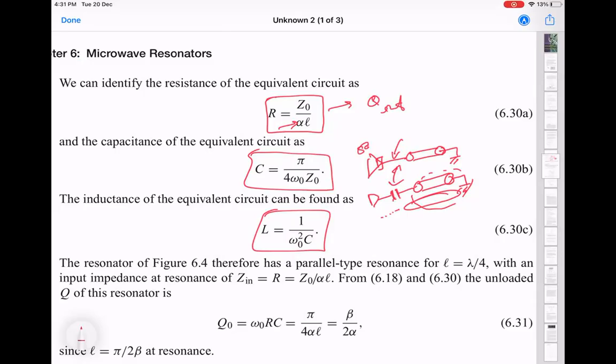So that is what the argument given in Kozar also is saying. You just cannot make perfect inductors and capacitors at those frequencies. Whereas a transmission line is very easy to make. It's just a strip of metal. And you're not making any other approximations there. Right? The modeling in terms of its microwave response is complete.